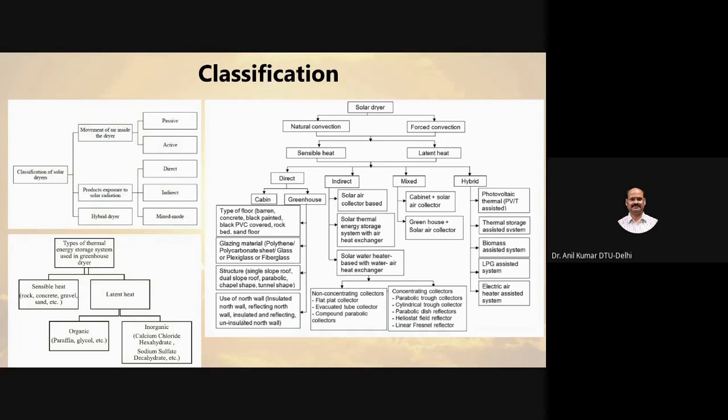If the north wall is transparent, then most of the solar radiation comes through the south wall and passes directly through the north wall, and these are basically losses. We can stop those losses by making the north wall opaque, and in this north wall we can utilize the energy storage material effectively.